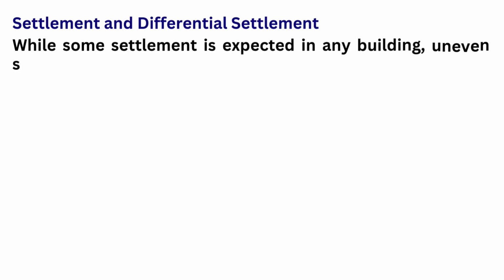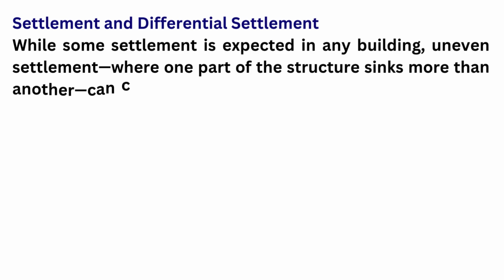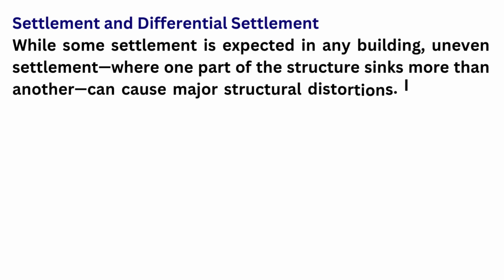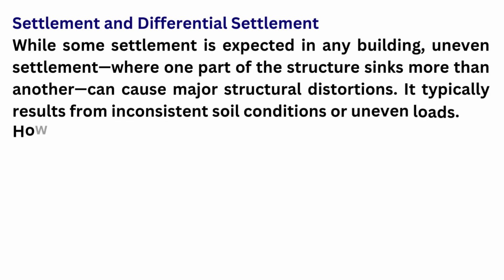Settlement and differential settlement. While some settlement is expected in any building, uneven settlement, where one part of the structure sinks more than another, can cause major structural distortions. It typically results from inconsistent soil conditions or uneven loads.